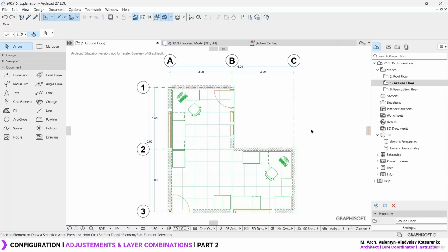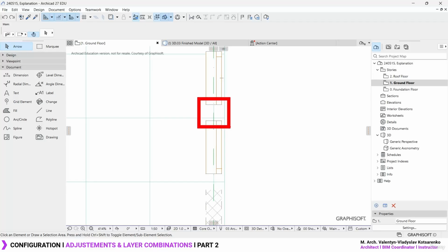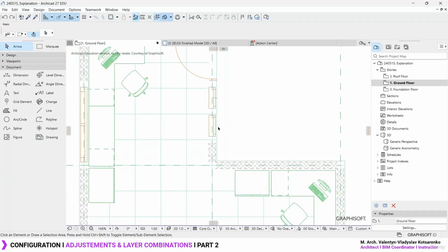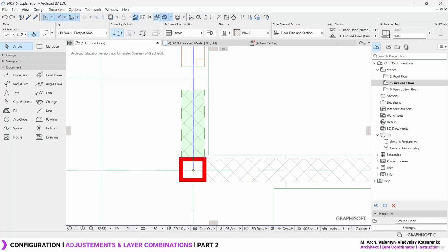Alright, so pretty much I'm done, and before we finish this lesson, you will notice that you have some type of trouble going over here, such as this one. You have these small gaps happening because you've got some type of column blocking the way. This happens because the masonry columns, the masonry pilaster, will automatically subtract a part of your wall, thanks to the priorities we have in the materials.